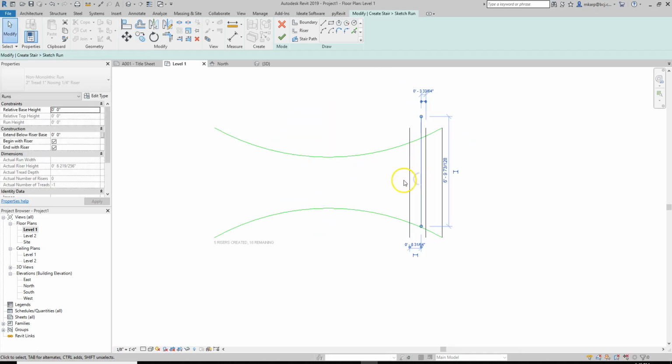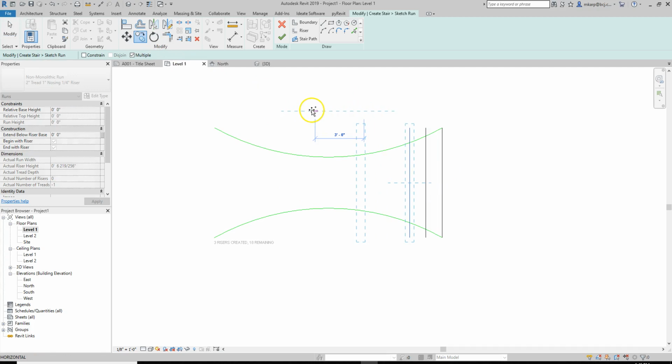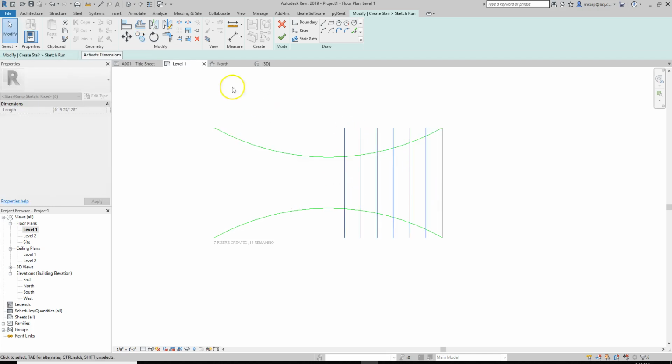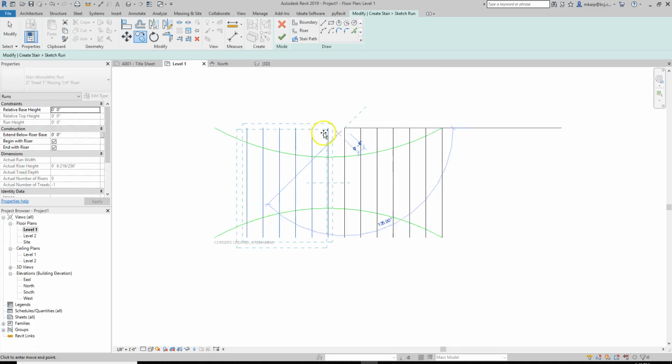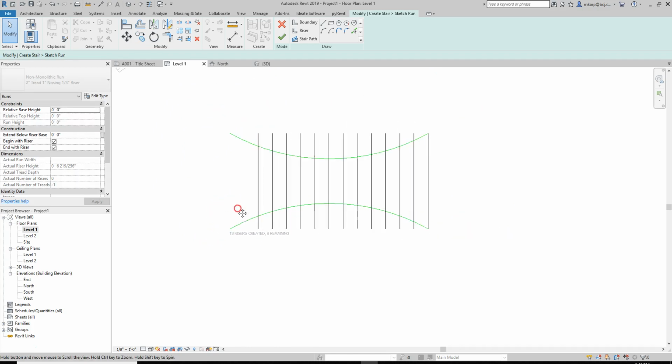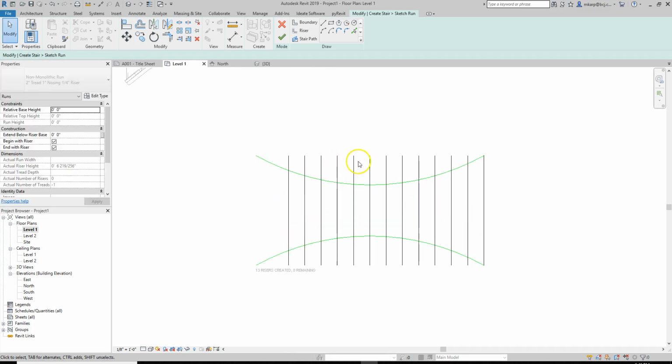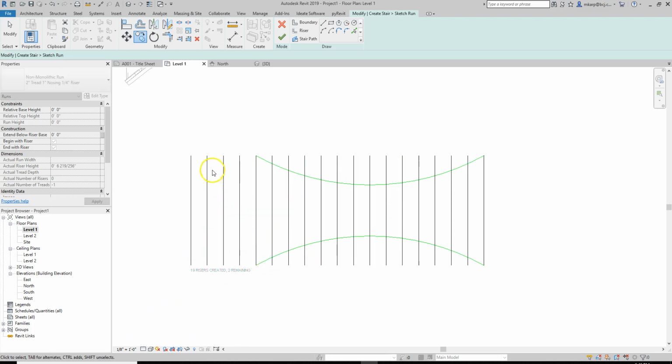well, we don't want to overlap them. That's bad. So we could start to do is have a staircase, a tread that is 1 foot deep all the way up. And I can even start copying these too. Alright, 8 remaining. I didn't draw these boundaries long enough. So let me just draw all the steps I need first, and I'll redraw my boundaries. I just need 2 more.